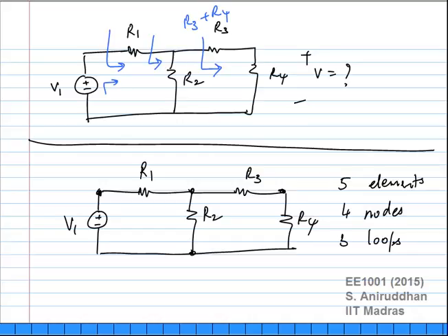Potential difference. KCL has to do with currents, right? It has nothing to do with potential differences yet. It may not be happening at one point, right? See, currents get added up at every node and they get added up to 0 because there is no charge accumulation, right? That is what we have been saying. But for any general network, how can you say that there will only be n minus 1 independent KCL equations?